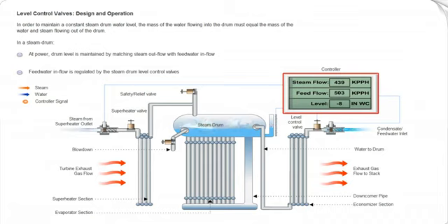When operating at power and when in three-element control, the steam drum level controller automatically maintains level by matching the steam outflow with the inflow of hot feedwater, making automatic corrections to the level control valves in order to maintain the drum water level at the normal water level controller set point.